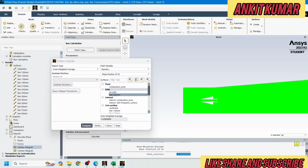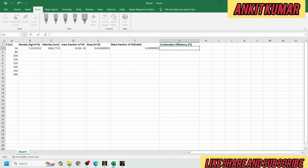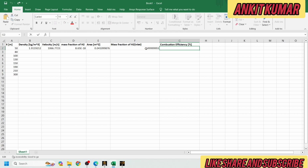I have already extracted this value here. So for writing the combustion efficiency, I will write it here: 1 minus mass fraction of the hydrogen divided by mass fraction of the hydrogen at inlet. It means the mass fraction of the hydrogen, this one, divided by the mass fraction of the hydrogen inlet, means 1 minus d2 by f2. So select this combustion efficiency block, press equal to 1 minus d2 by f2. Either we can take one bracket and write d2 by f2 and close the bracket, then it will automatically select d2 and f2.